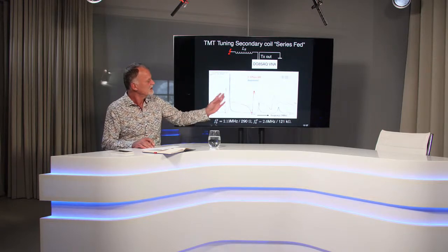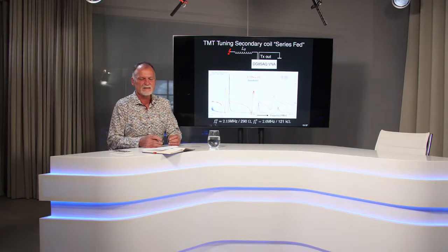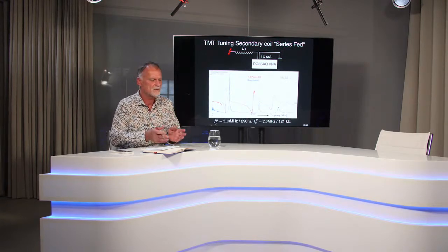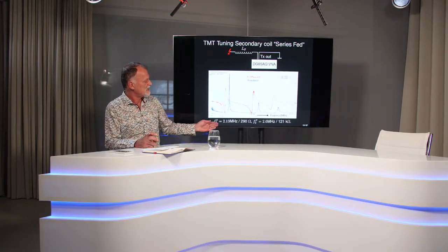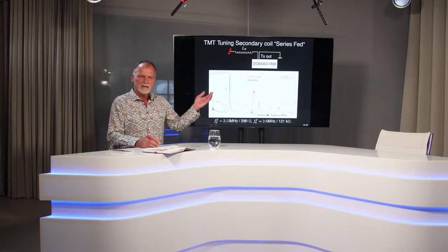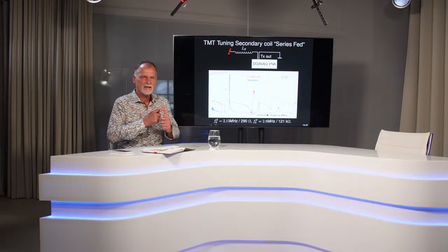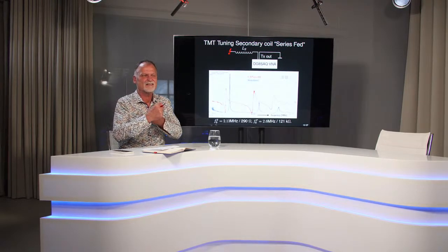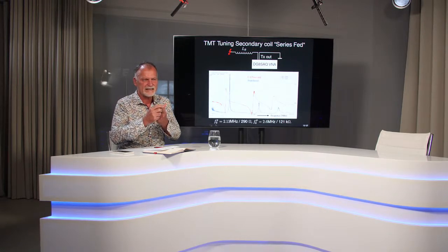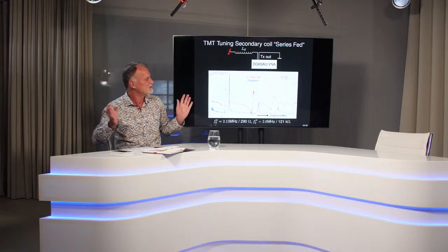So this is a very interesting plot which you can do with this VNA, which allows you to characterize every single coil before you use it for any measurements and so on. The idea, what we are learning as we speak, is that if you are designing the secondary coil, you have to take into account the lambda/4 effect. So you have to choose the right wire diameter, and the right coil diameter, in order to get the aspect ratio close to 5, and many other things like that.